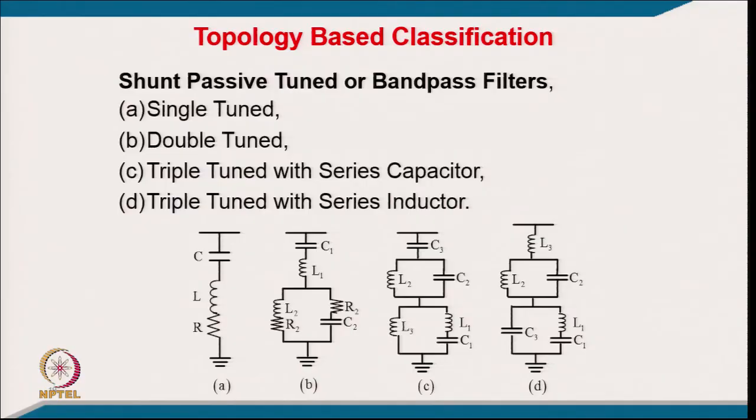Otherwise, ideally there would be infinite current if completely tuned, since L and C impedance would be 0 and even a very small voltage would give infinite current. But practically it cannot be that. So practically, the resistance limits the current of that particular harmonic, like the third for single phase and the fifth for three phase.